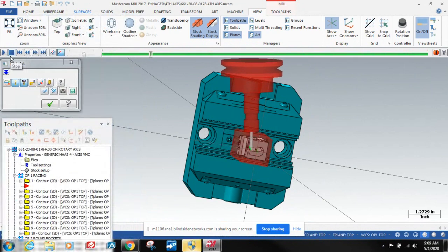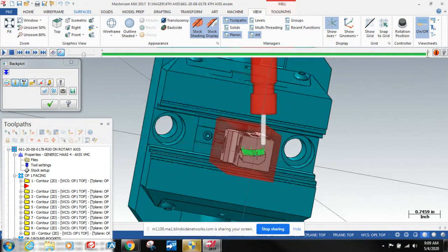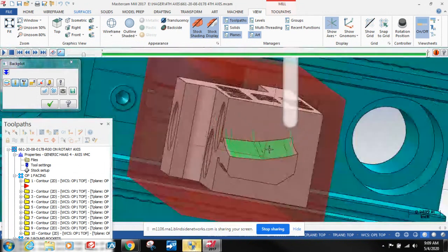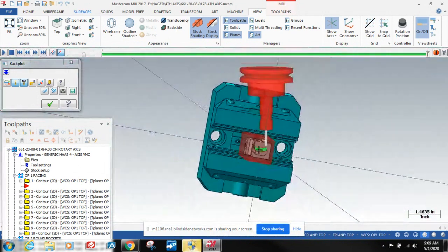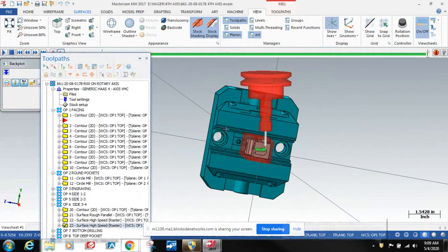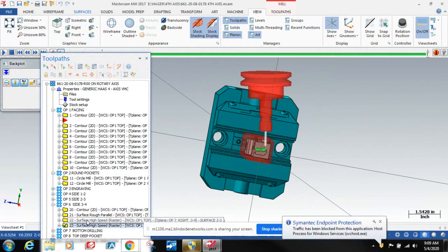You can see the only movement there is up and down and left and right with the spindle. There's no rotational movement in that toolpath. It's just already been positioned. There's no A. Once you get it into position, then it makes up the rest of it in X, Y, and Z moves. There's no A rotation moves there, and it does that whole surface.